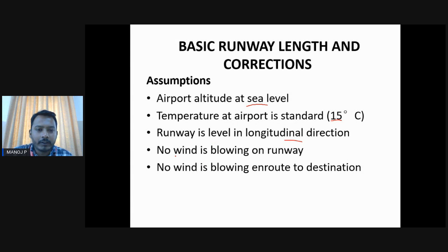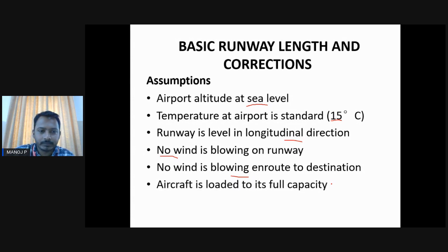Okay, the runway will always be level as per their assumption, and no wind will be blowing on the runway, and also no wind will be blowing en route to the destination. All these are the assumptions. We need to make corrections while designing a runway, while calculating the basic runway length and corrections.